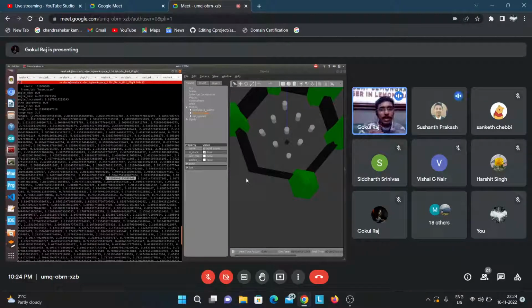So you can use that particular data and write two codes. One is publishing the command velocity to go straight. The other is subscribing to the scan data and checking this particular value. If that value is, like, 1.9, it means at 1.9 meters there is an obstacle. If this is less than 0.3, that is 30 centimeters, if there is an obstacle, it will publish stop. So your command code will stop the robot, like it will publish 0. When the obstacle moves, this data will increase again. Then the if statement will break because the distance is greater than 0.3, the obstacle flag will be false, and your command can publish velocity, so the robot will move forward. This is how you can use Gazebo.